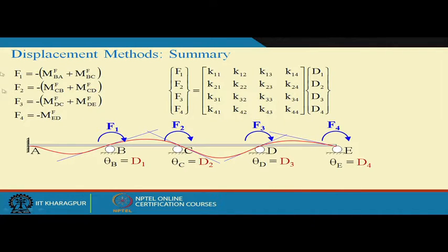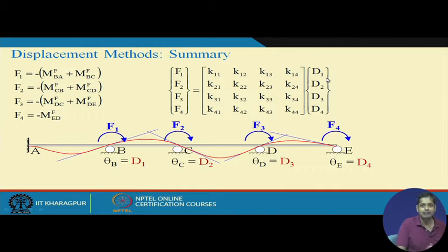Now, the direct stiffness matrix or matrix method of structural analysis is essentially this. One premise of this method is that you divide the entire system into small systems, get the information of all the systems, and then assemble them. Depending on the problem you are dealing with, that decides what information you need. If it is a structural analysis problem like this, our information is how the forces and displacements are related to each other.